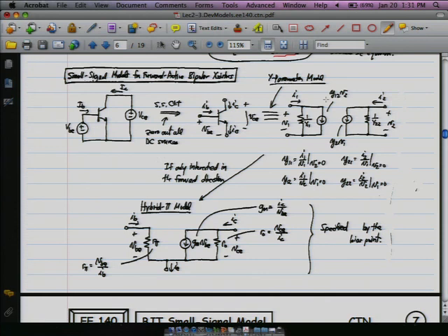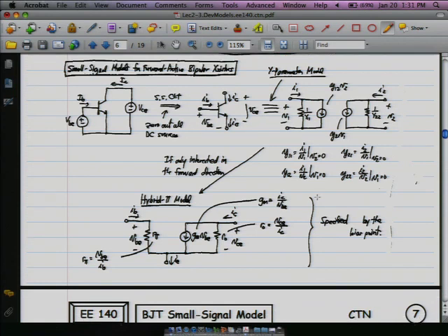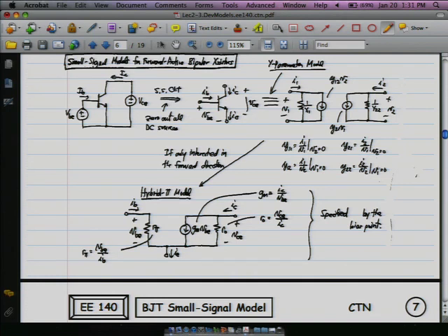And so these are right now expressed in terms of these y parameters. So there's y11, y12, y21, y22, and it's basically just the ratio of the current and voltage, setting one of the other parameters equal to 0. So I won't spend too much time on this. Just know that it exists, keep it in the back of your mind for later in the semester. And at some point, we will come back to it.